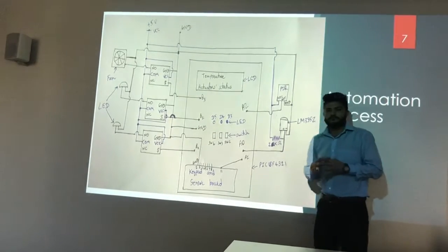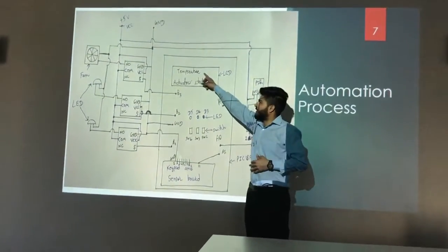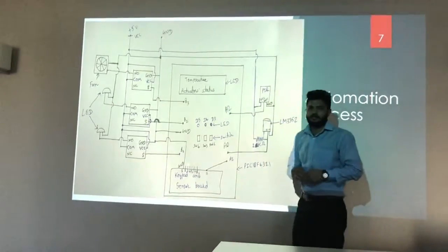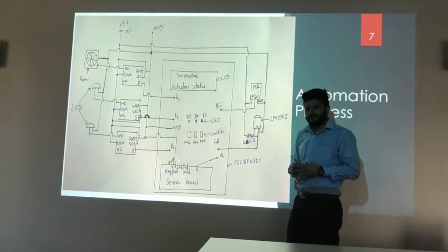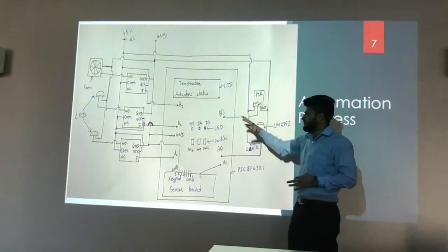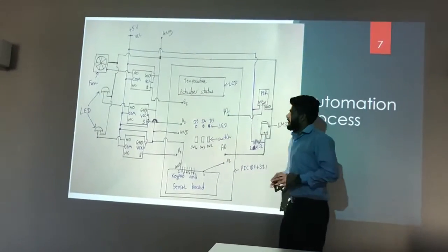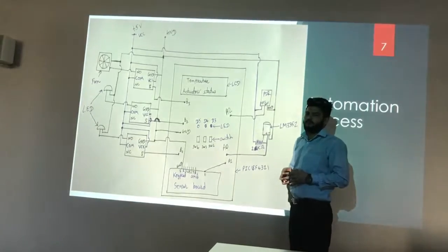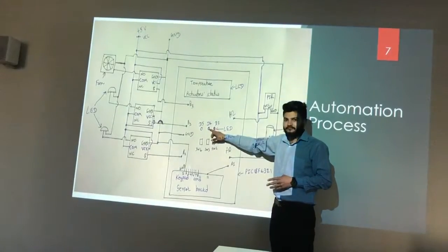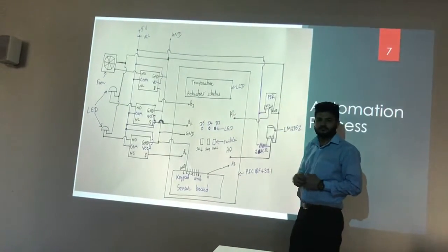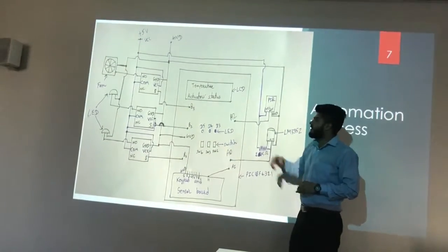When I start the program, it will show on the first line of the LCD of the PIC board that it requires a password. If I enter the password wrong 3 times consecutively, it will lock, and it will show lock on the screen of the LCD. Then I programmed it so that if I press switch 3, it will blink LED D4, and it will reset the system, and it will start from the beginning.